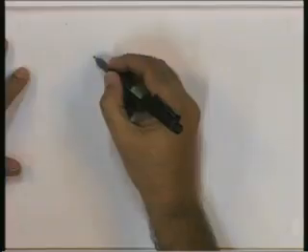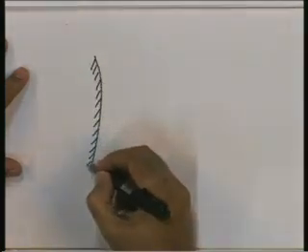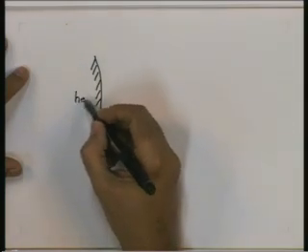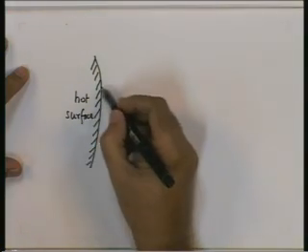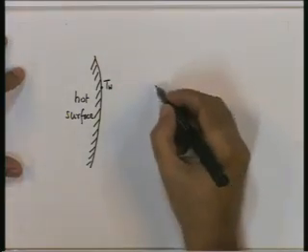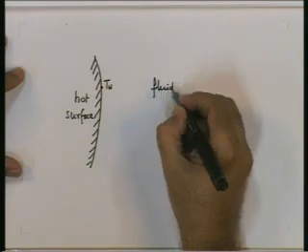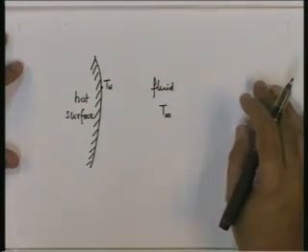If we look at a situation of natural convection, we will see the following. There is no bulk flow during natural convection. So, if I have a surface, just showing some surface, which is say hot, at some temperature Tw, and it is immersed or exposed to a fluid at say T infinity, away from the plate, uninfluenced by its presence.